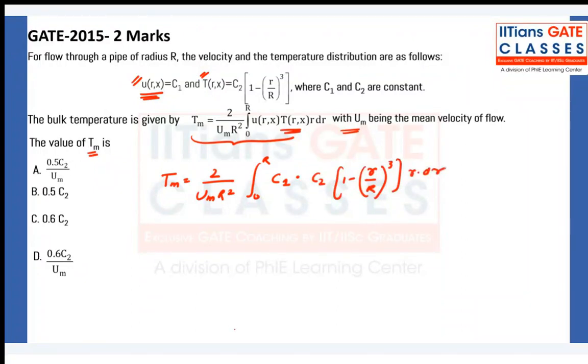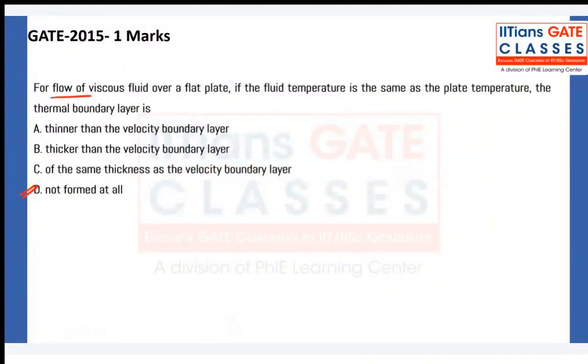No, hydrodynamic boundary layer will form, because it forms because of the velocity. That will always form. If it is moving, if any velocity is there, they did not tell about velocity. If it is moving at a velocity, then here velocity is 0, and away from this velocity is u infinity. So of course it will be formed. Of course there will be a velocity gradient, and of course this will form like this.